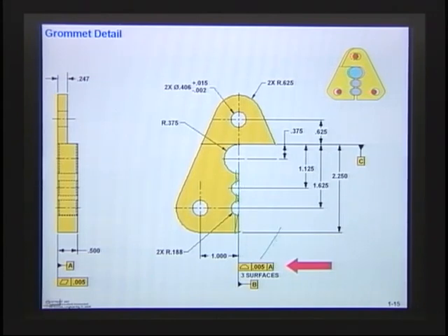And again, why I showed a tolerance there of 5 thousandths was because, remember, the mating part comes up to this, and in this area right here, we couldn't have a gap any more than 10 thousandths. So I put profile on this within 5 thousandths. The other one had 5 thousandths. That's going to give me a max gap of 10.